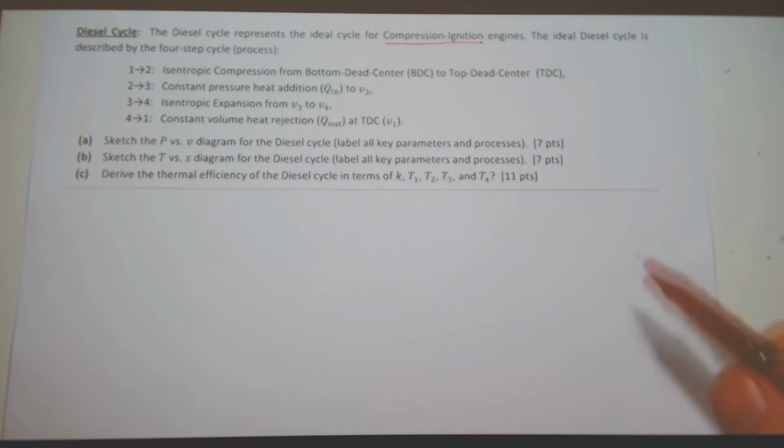So basically, you compress something to the point of auto ignition. So if I take a banana and I put it in a piston cylinder exposed with air, and I compress it, I increase the temperature and pressure of my banana fuel air mixture, okay?